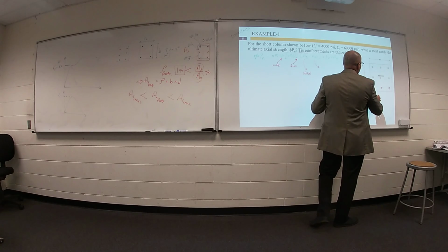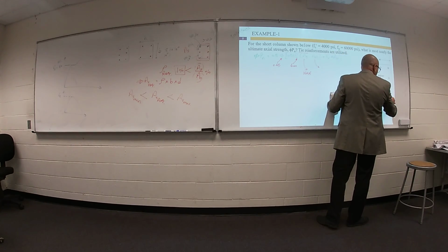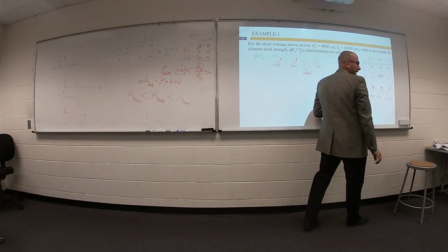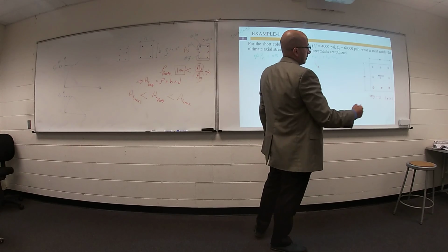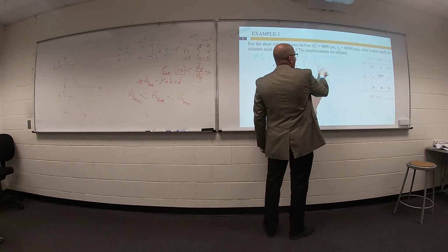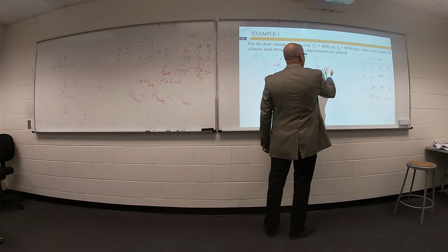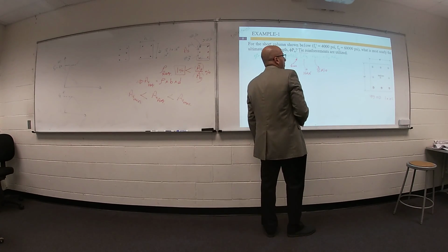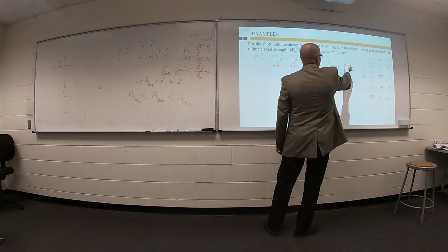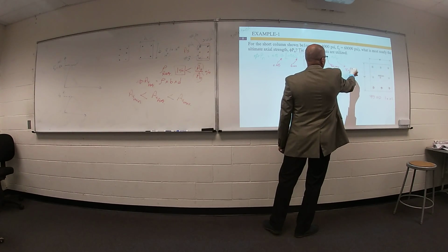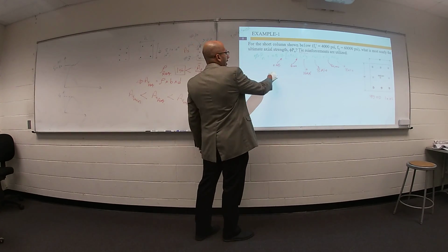For a number 9 bar, what is the area steel? I think 1 square inch. But we have 8 bars, so your area steel will be 8 bars times the area of 1 bar, 1 square inch. fy is 60,000. Area steel is 8 bars times 1. That's all. You can figure out the rest.